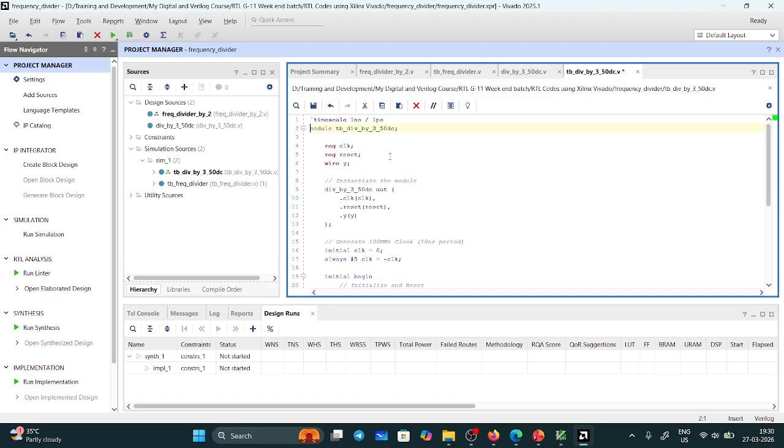Those PLLs will multiply or divide the frequency in such a way that, in order to synchronize, they should operate with 50% duty cycle. Is it fine? No, no, synchronization will not happen otherwise. It should operate at whatever the frequency, with the 50% duty cycle.